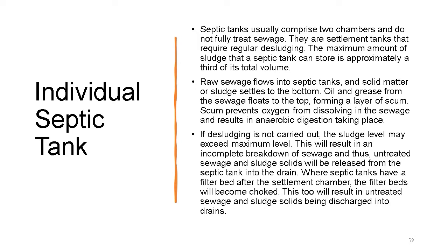Where septic tanks have a filter bed after the settlement chamber, filter beds will become choked, akan tersekat lah, sebab solid metals and whatnot akan block that filter beds. These two will result in untreated sewage and sludge solids being discharged into drain. Jadi akan masuk pada drain. Ini akan menjadi pollution lah, sebab dia akan directly masuk pada drain.